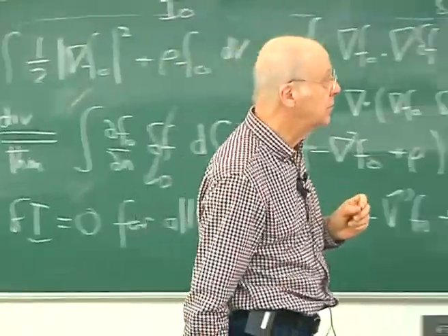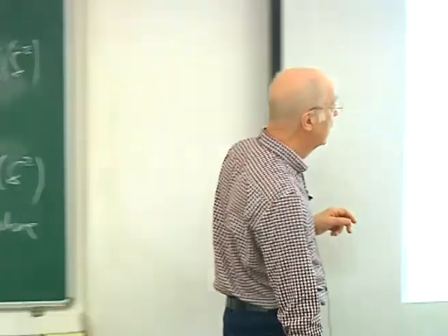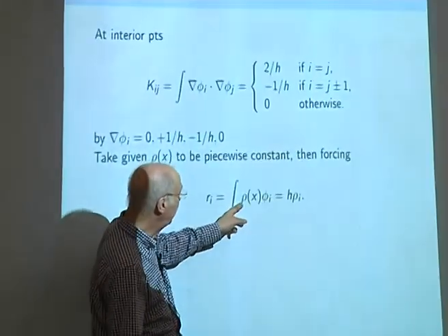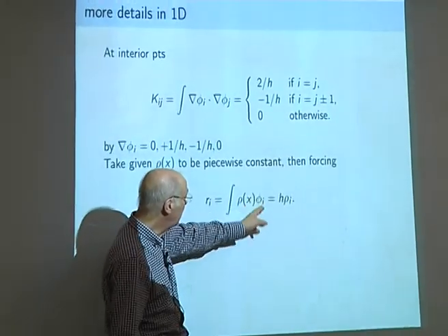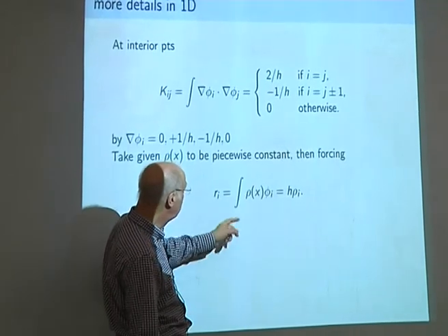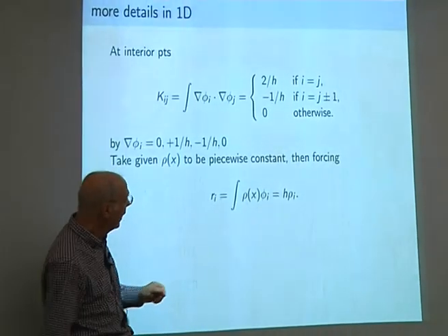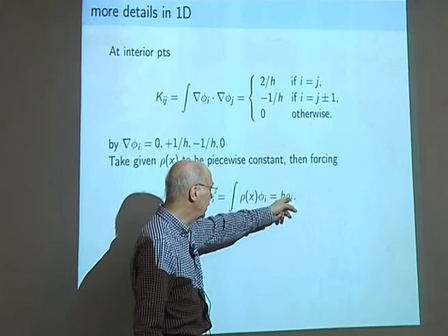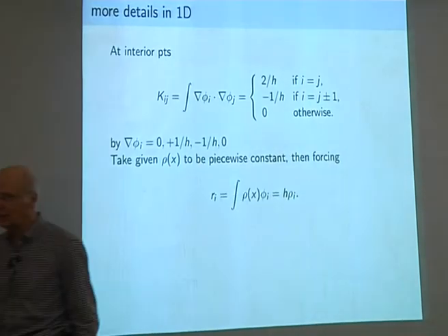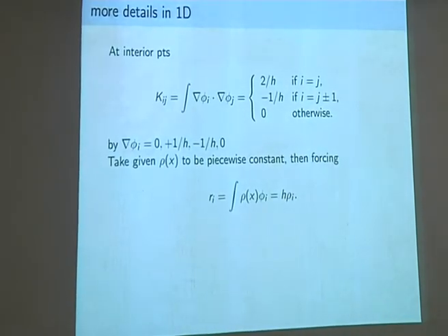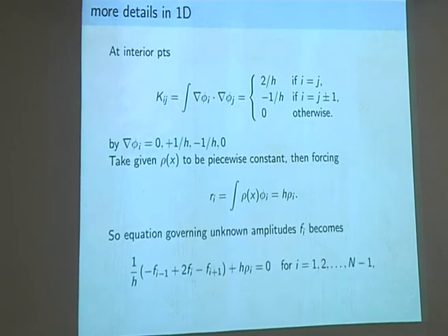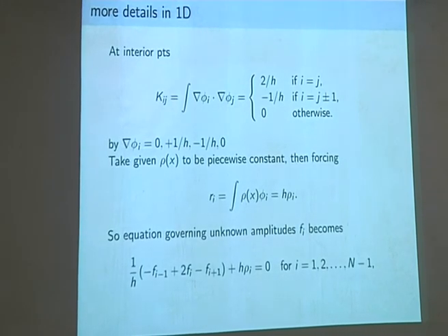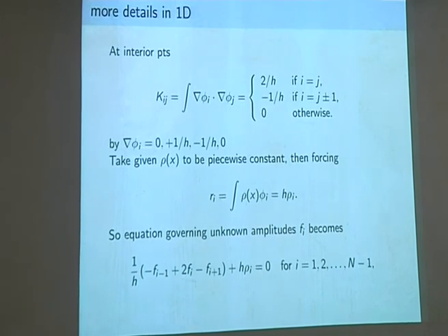And then this is effectively, so we have a linear variation over a triangle, and I'm going to say that that is the value of the function in the middle somehow, being slightly vague. So the governing equation turns out to be this. And that's pretty familiar. It's the same as finite differencing.